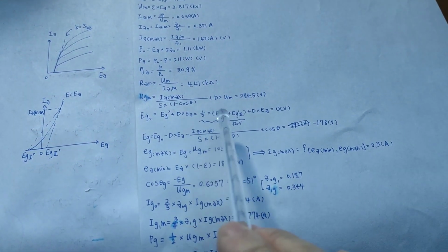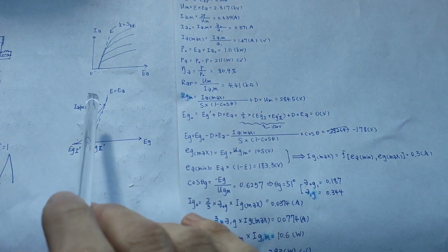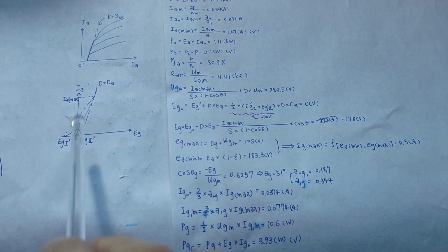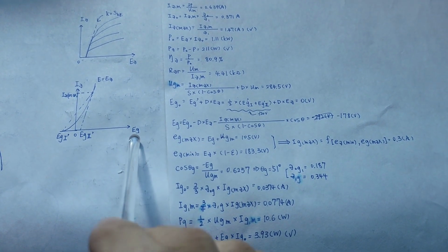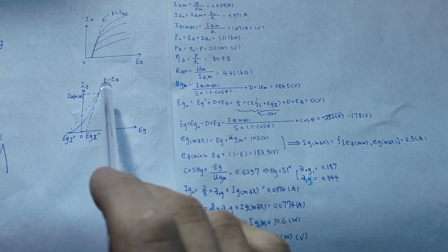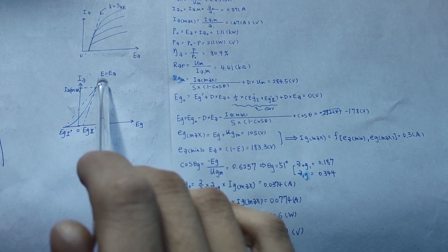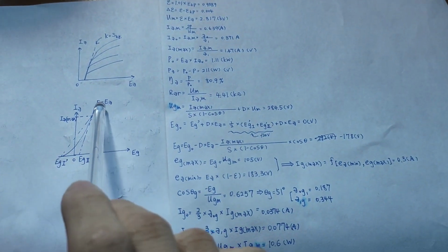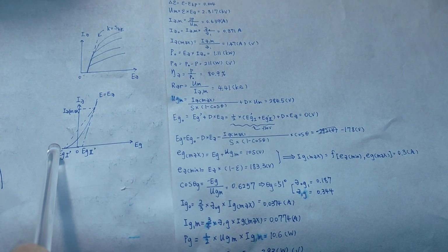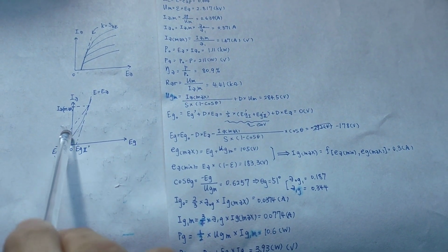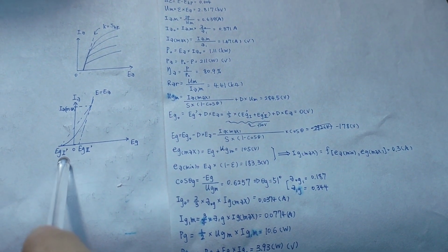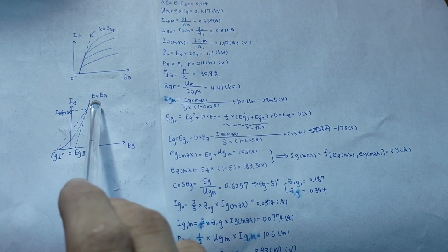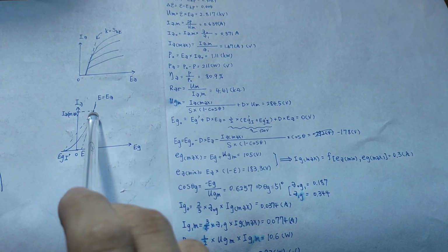I still need to tell you how to calculate it. If you check your PDF documentation of a vacuum tube, you can also see this kind of graph, the anode current against the gate voltage. So you choose a line which represents the working condition of your input voltage, and this line will have a cross with this axis at this value. This is usually a negative value, which you can put in here, and you need to draw a line at this certain point,